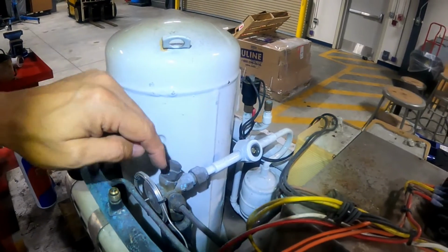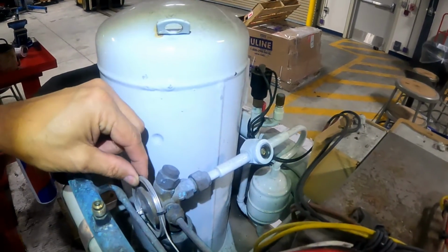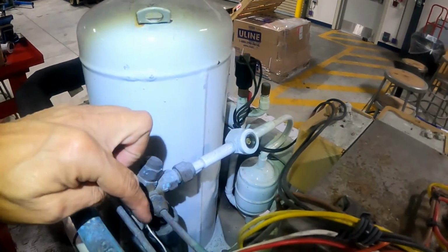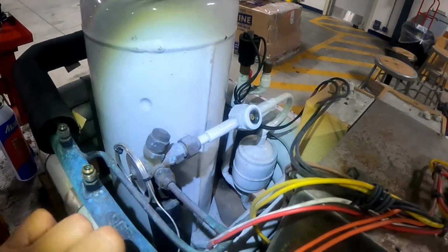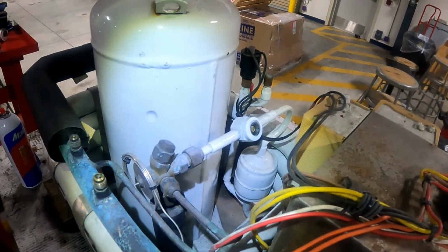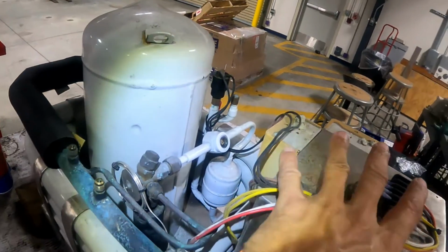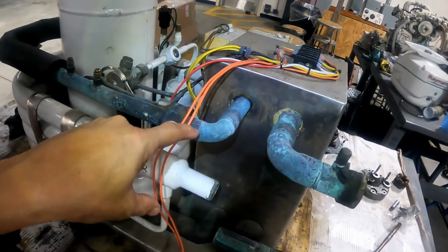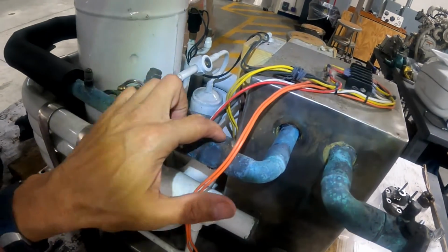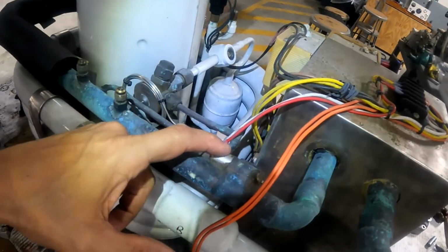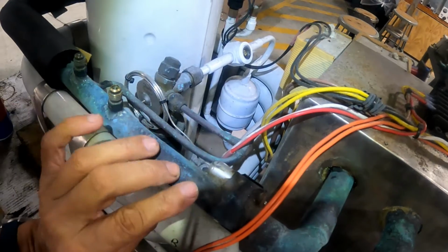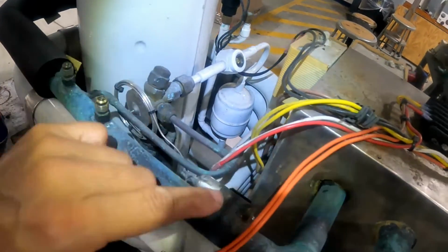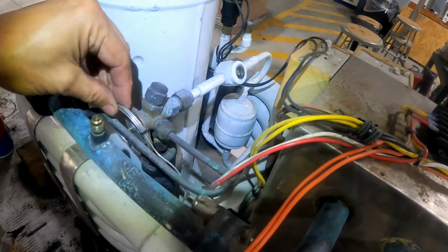The expansion valve opens and closes depending on the signal coming from this capillary pipe that finishes in this bulb. This bulb is located at the output of the evaporator. This is the output of the evaporator, and here is located the bulb. The bulb sends the temperature of this pipe, and according to the temperature of this pipe, sends the signal to